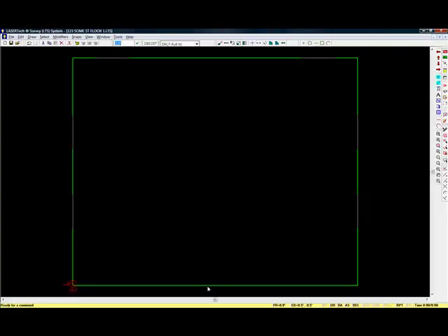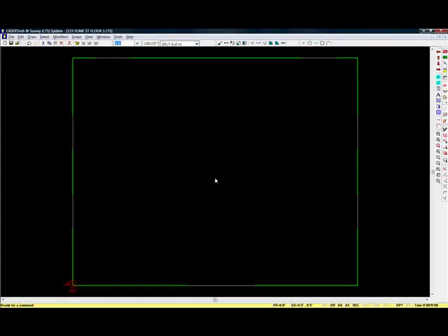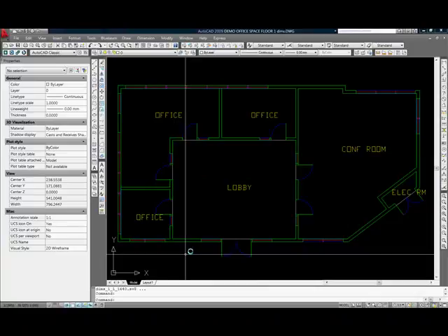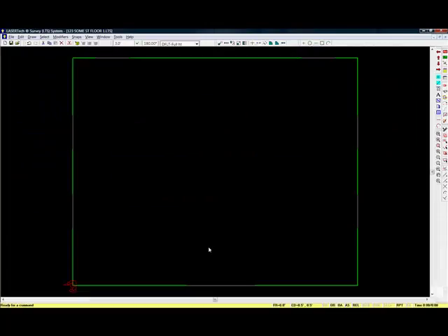Now this is our front door here, and we're going to put a double door in here eventually. And so we're going to come over from this corner here 10 feet, and we measure it, and it's a 6-foot door opening. Now we save again, and the next thing to do would be to put in windows if there are any. And let's just have a look at our AutoCAD drawing. You can see there's a couple of windows here either side, so we'll put those in for now.